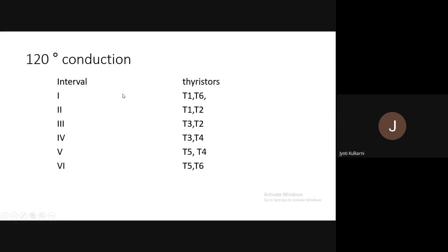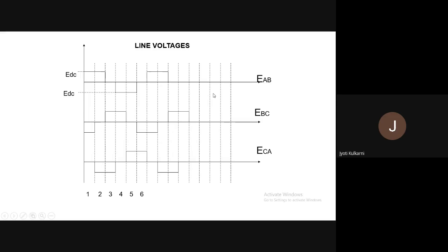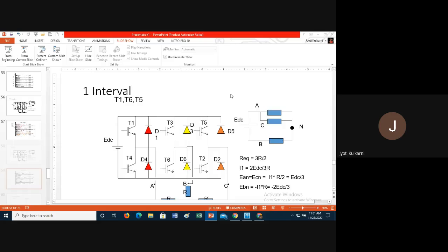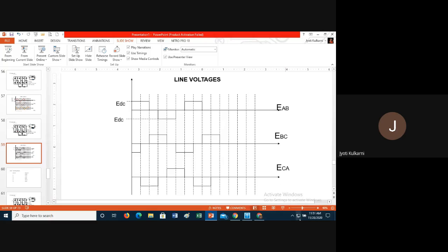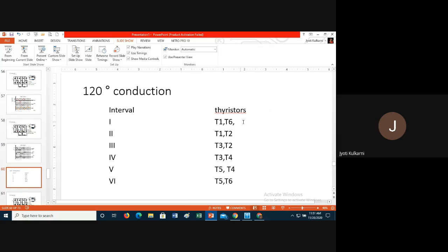Okay. So this is 180 degree conduction. To thoroughly understand the waveform, you are supposed to work on it. I know that within this half an hour discussion we cannot understand, or you cannot clearly do your concepts well. You have to at least do some paperwork, and with this paperwork you will be able to do that waveform pattern. But if you know 180 degree conduction, it will be very simple to understand 120 degree. 120 degree is very simple because there are only two devices.